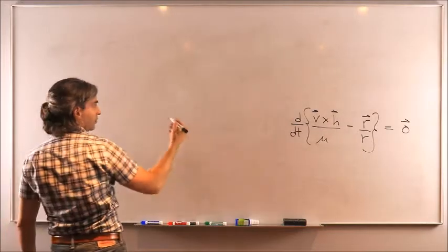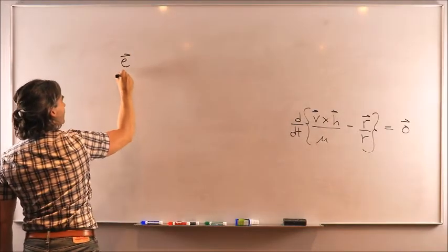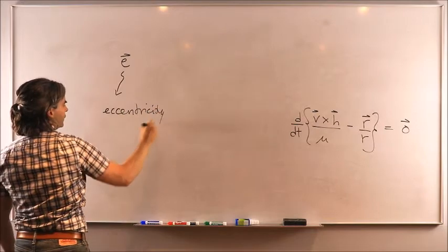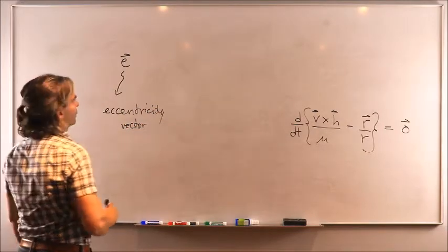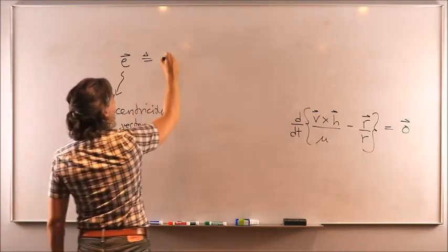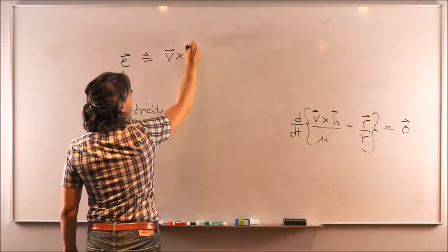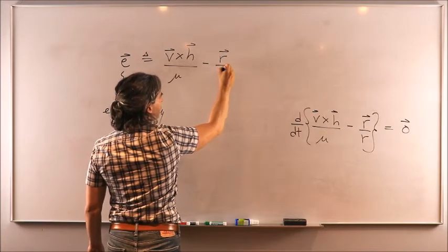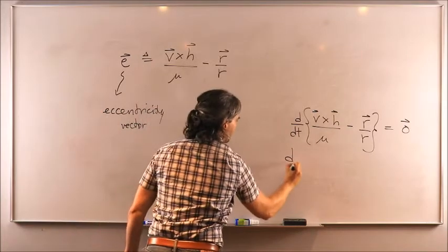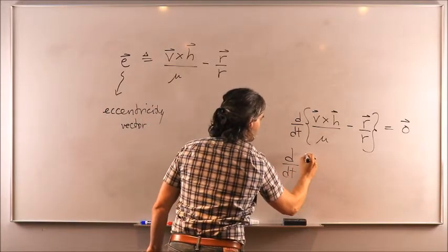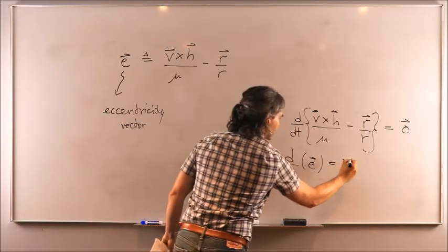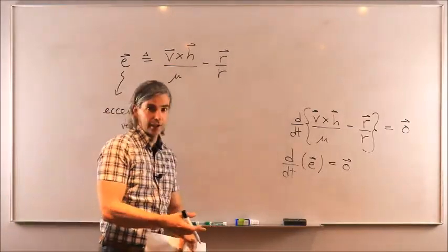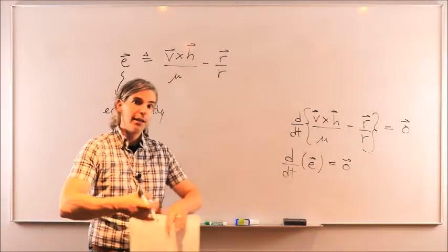Which, from that last expression, we can then infer that the eccentricity vector, denoted by E vector, has to be equal, and it is equal by definition, to velocity cross product orbital angular momentum over mu minus position vector over distance, which means that we have indeed achieved the objective of showing that the eccentricity vector was the third fundamental integral of the two-body problem, or in other words, that the eccentricity vector alongside the orbital angular momentum and the orbital energy is being conserved.